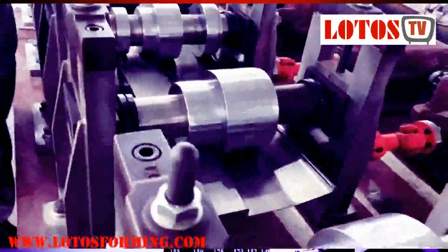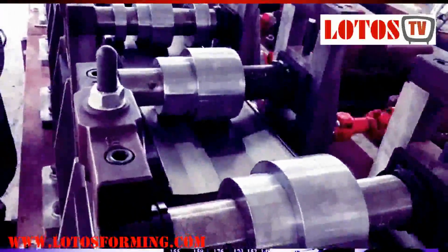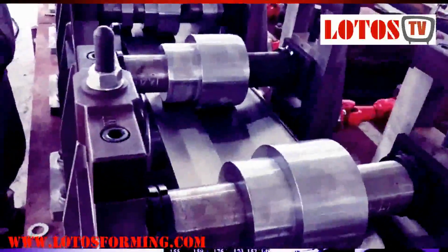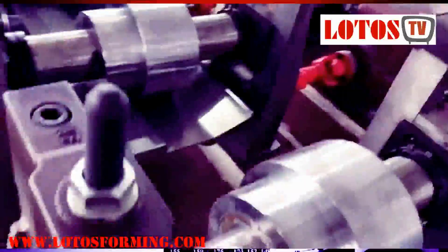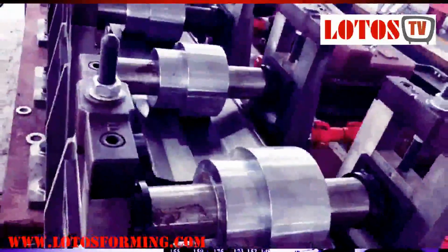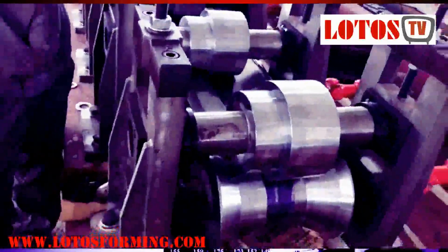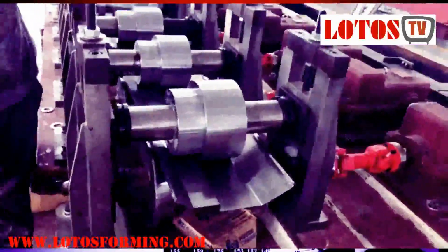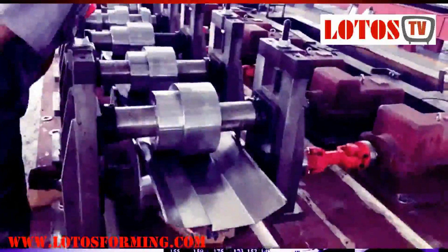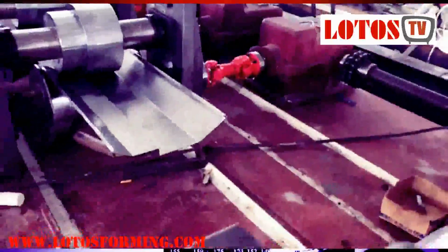The data can be looked at in different locations to compare, but here, due to the time limit, I only show one of the locations, where we can see the plastic strain is highest at the top of the dimple, and then reduces to somewhere close to the middle, and then increases again.